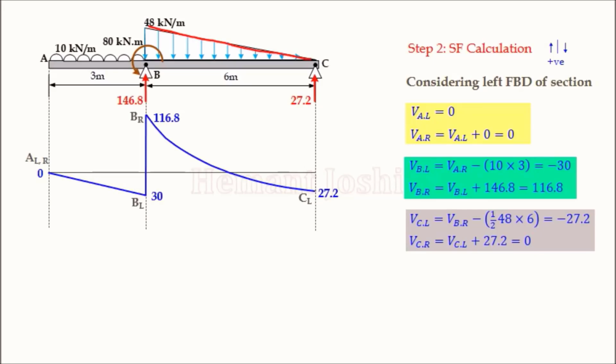The only point of investigation is whether the parabolic curve is concave up or down. So remember that table and logic. This UVL is downward and decreasing, and we know that for downward UVL decreasing, the concavity is on the upper side. So this is the curve having concavity at the upper side. Parabolic curve of second degree, concavity up. This point is now plotted.